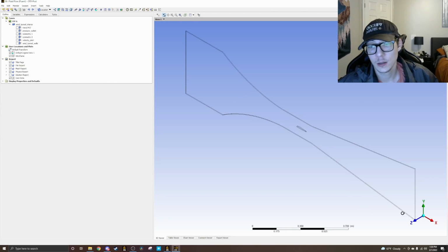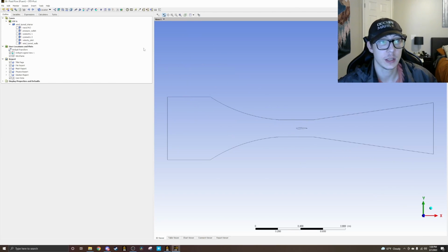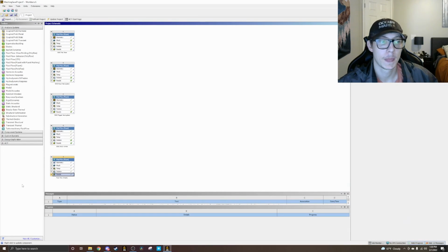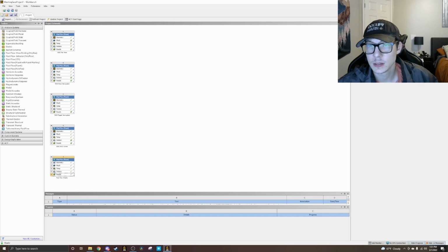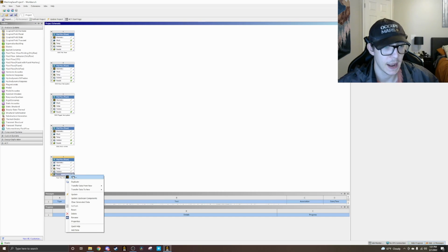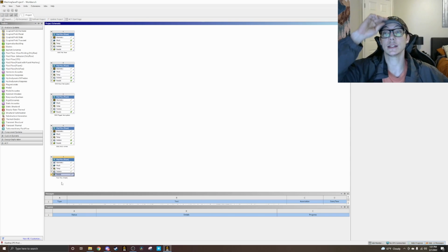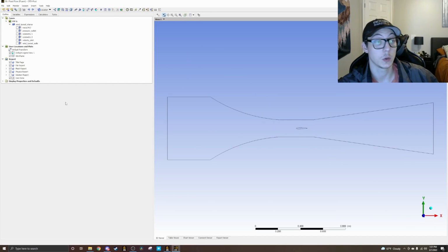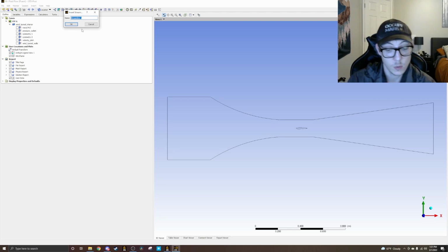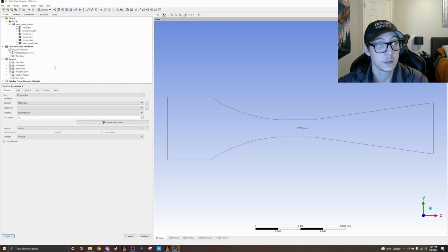So we'll let it think. Bring this over here. Let me see if there's actually an option to, so let's edit this. Let's go into properties. Yeah, there's no 2D option that I see. So we're just going to go back to editing this. So now that we're finally in the results page, we are going to go ahead and do a streamline. So click that, streamline 1. That sounds good to me.